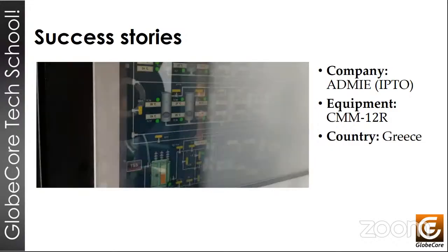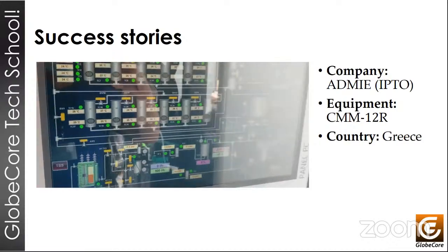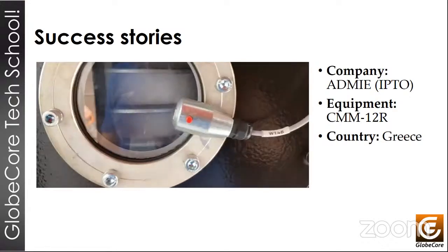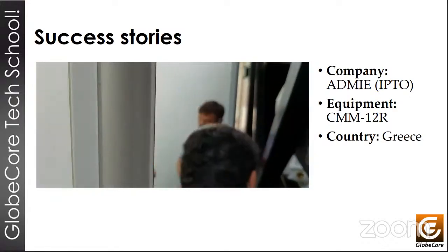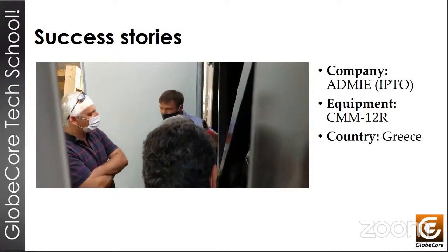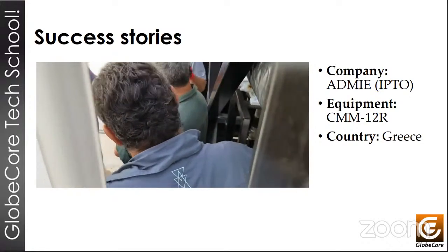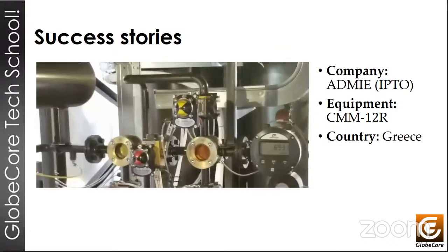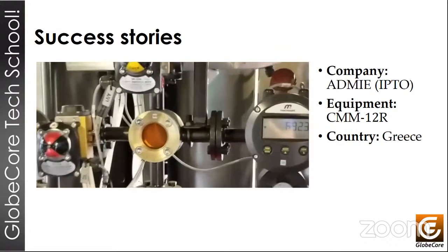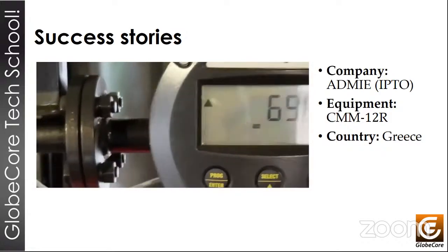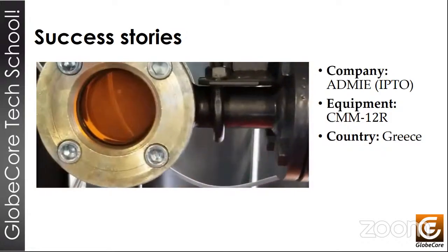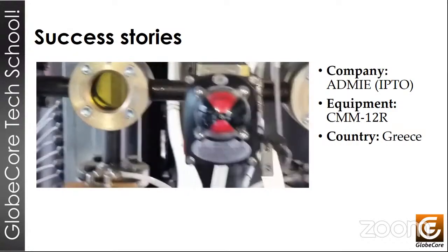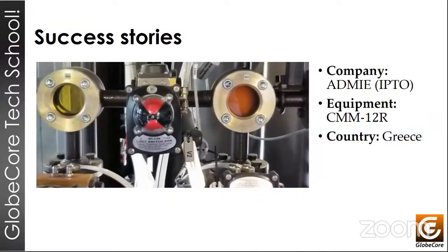The process was done in 2 passes through the regen columns, and between the passes, the sorbent in the column was reactivated. I promise I'll tell you how this works in a minute. The reactivation process between the cycles took 15 hours and was done automatically by the unit's PLC. You can see here in this video the 2 side glasses. This is the flow rate through the plant. This is the incoming oil. You can see how dark that is. And this is the regenerated oil, much lighter.